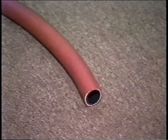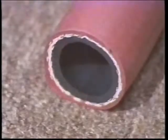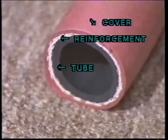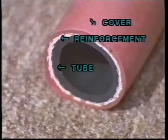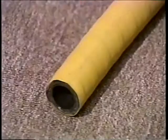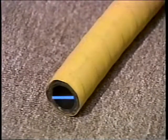Let's begin the study of industrial hose by looking at the components of our flexible pipe. Most hoses have three component parts: tube, reinforcement, and cover. The tube is the inside portion of the hose that is in contact with the material being transferred. The inside cross-sectional measurement of the tube is the inside diameter. The inside diameter, or ID, is the basic identifying dimension of the hose. For example, a 1-inch hose means that it has an ID of 1 inch.